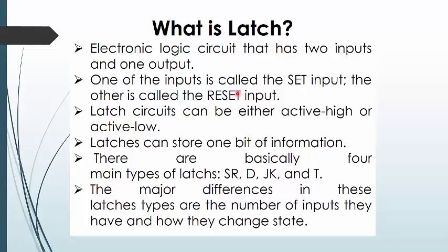For a latch, set and reset are the two inputs, and these latch circuits will be either active high or active low. But definitely these latches store a single bit of information every time, because the latch has two inputs but only one output, and that's why we say that latches can store one bit of information.